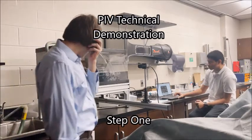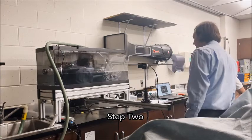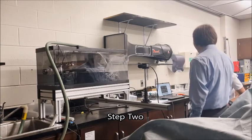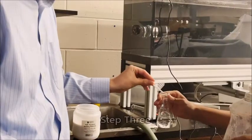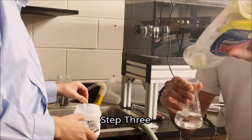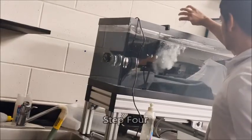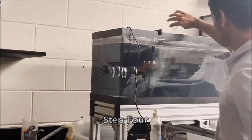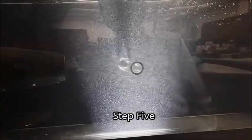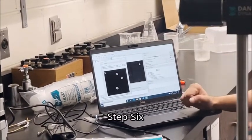Fill the water tank. While the tank is being filled with water, connect the software dongles and camera to the computer and load the Dynamic Studio software. Mix 2 scoops of the seeding particles with 100 milliliters of water and 2 drops of dish soap. Add the mixture to the tank. Turn on the pump and the light sheet. Enter acquisition mode on the Dynamic Studio software.